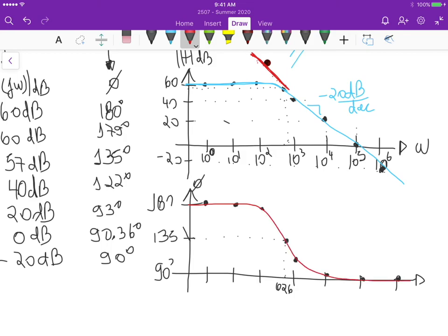It goes just right like that. So you see that at higher frequencies, we still have the same 90 degrees that we have on the first circuit. But now, because we have inserted that feedback resistor, we have changed the phase. Also, we have changed the phase for lower frequencies. So it goes from 90 up to 180 once we go for lower frequencies.